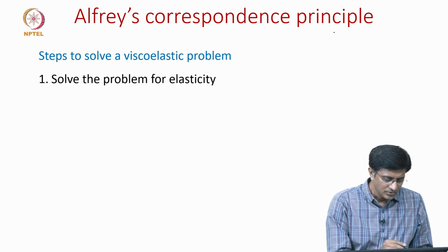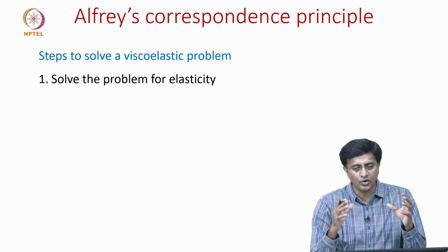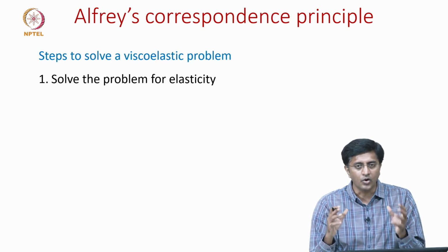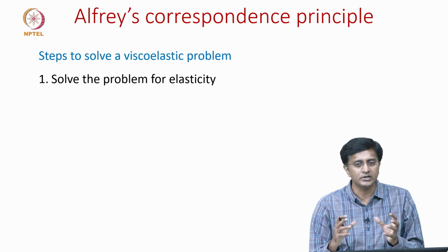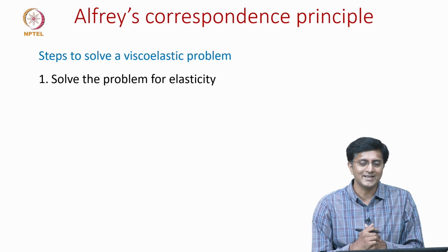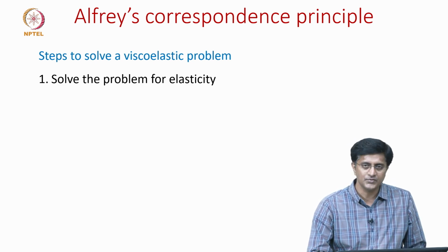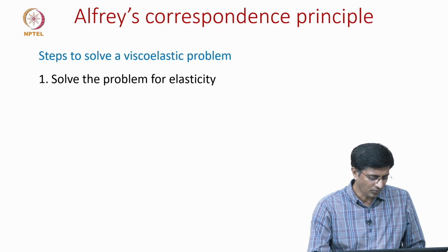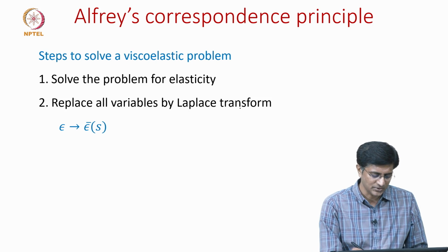First, solve the problem for elasticity. Meaning, you know what loads are applied on the body and what the boundary conditions are, then solve it in the elastic domain, applying elasticity to find the solution to that problem. Once we find the solution, then we replace all variables by their Laplace transform.